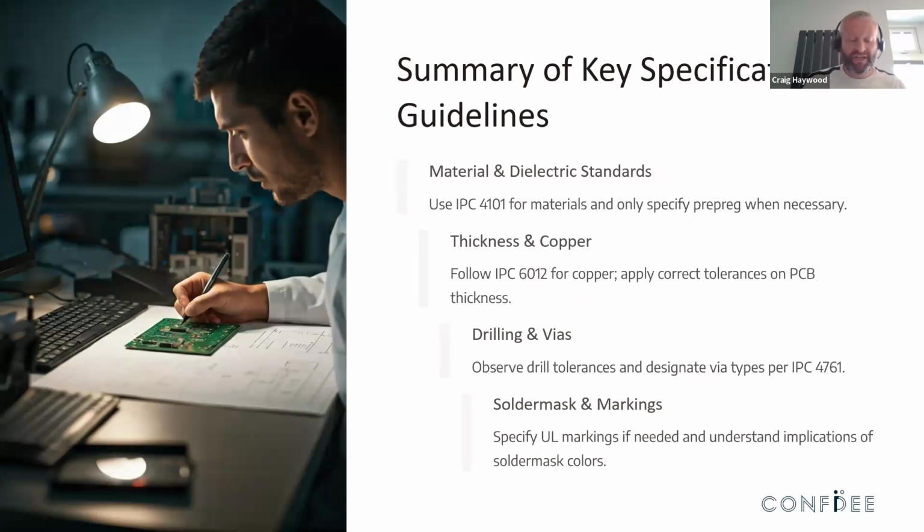So just as a summary, all of this is aimed at keeping manufacturing designs within capability, better yields, better pricing, better lead times. Follow the IPC standards as much as possible. Don't overcomplicate the notes by adding different material types or adding different solder mask colours if they're not really needed. Try and keep everything brief, try and keep everything clear. And then if you have additional requirements that aren't within something that has been just raised here, or something else that you feel is needed on the drawing, make a short summary.